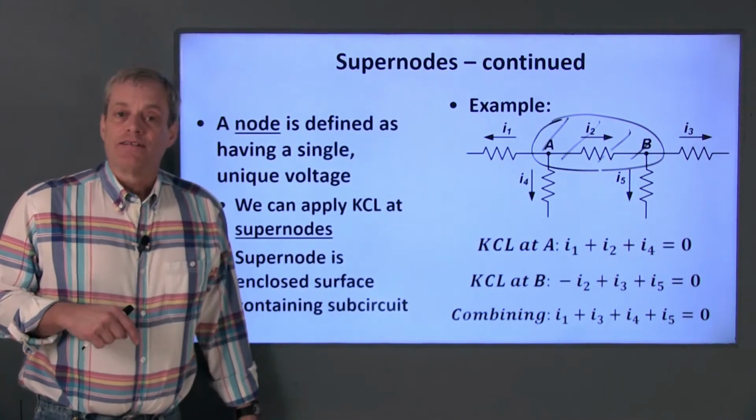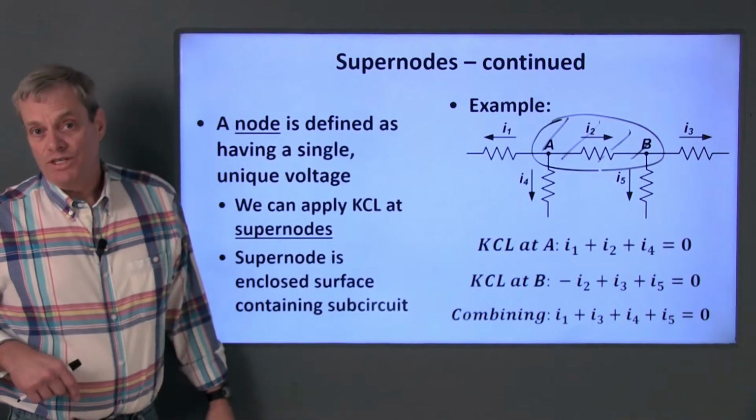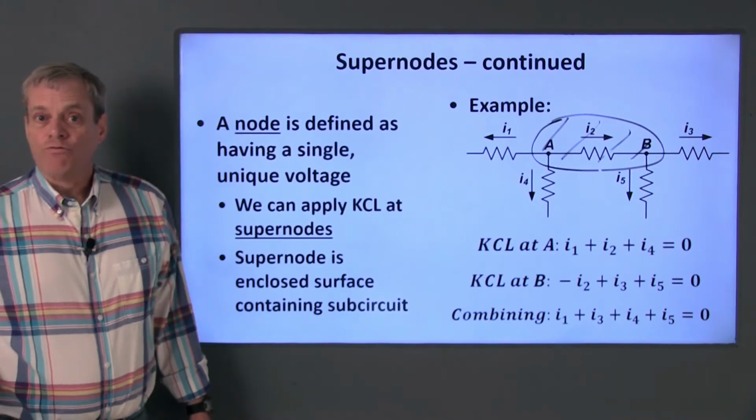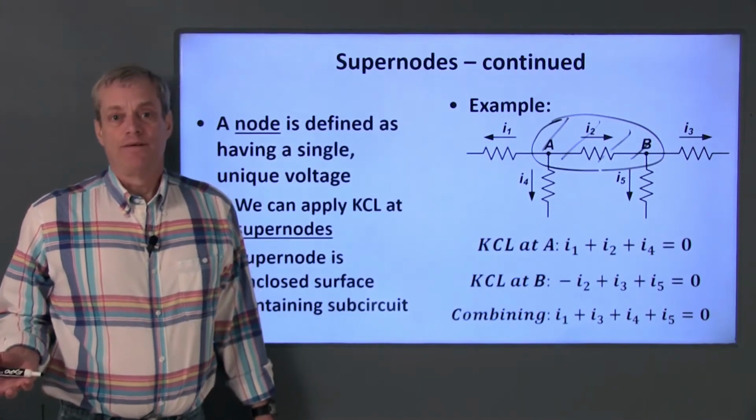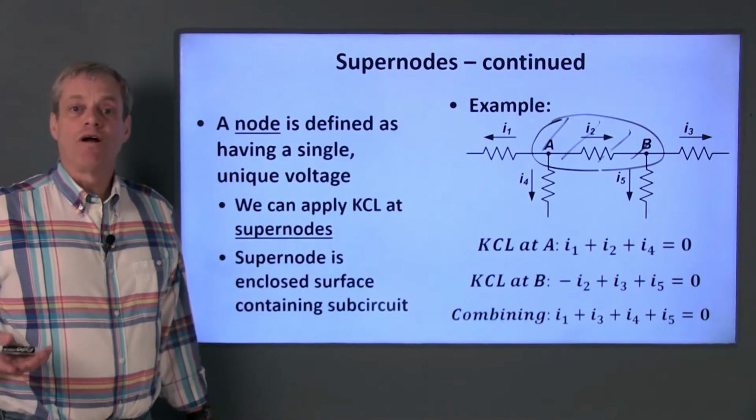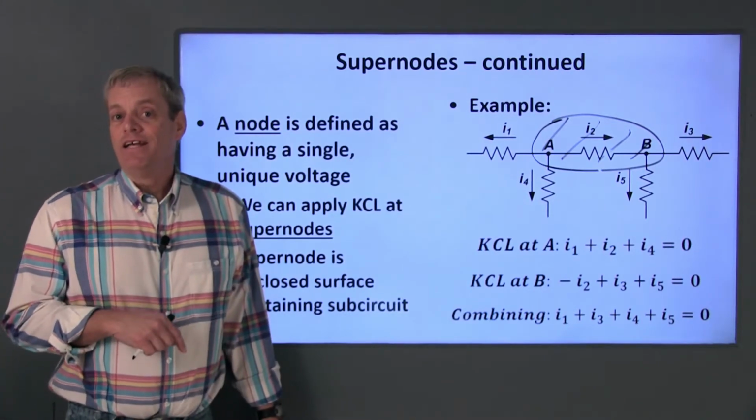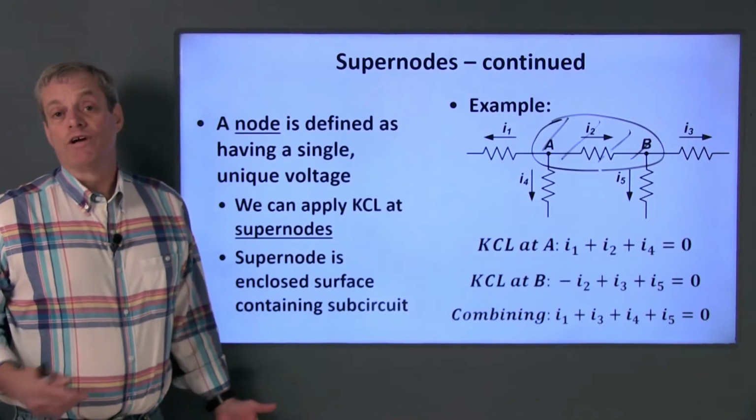Since in nodal analysis we're just interested in the node voltages, defining the current through a voltage source doesn't benefit us. Therefore, defining supernodes around voltage sources eliminates an unknown that we have no use for anyway.